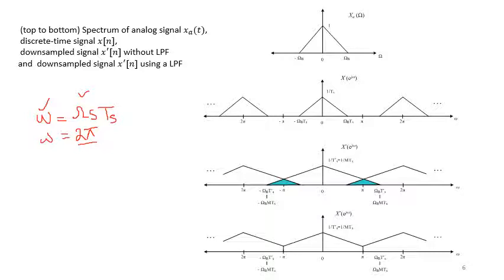So in case of the discrete time frequency, right, we have those replicas around 2 pi, right? So we have the first replica around here, then around 2 pi, around 4 pi, 6 pi, and so on. Or if we come to the negative axis, we have around minus 2 pi, minus 4 pi, and so on. So that's what we see, and it's also scaled by a factor of 1 by ts. So that's what we see in the discrete domain, right? So for the discrete time Fourier transform, we have this thing. Now if we